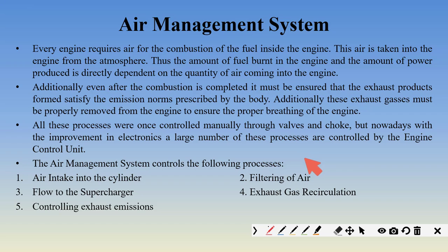It will be required to know what is the current speed of the turbocharger also. So there will be an RPM sensor of turbocharger also that will measure what is the current RPM of the turbocharger. The most important one will be the intake manifold pressure sensor. It will measure what is the amount of pressure that is being developed. Also there should be an exhaust gas temperature and exhaust gas oxygen sensor to measure the quality of exhaust so as to determine how much intercooling should take place.